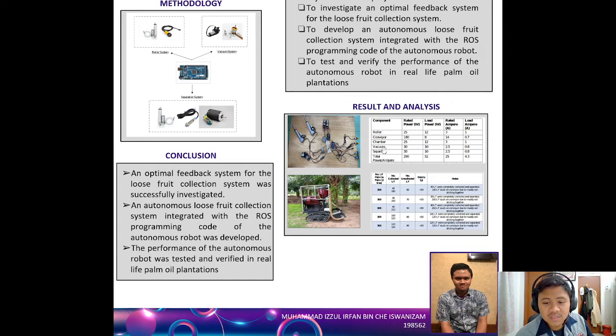It is also mentioned that the sensors are not considered in this analysis because the total watts used by each of these sensors are very low, and thus we can ignore these consumptions. And we also compare the rated amperes and the load amperes of the components. And we find that the total rated ampere is 25 amps, whereas the actual load ampere is only 4.3 amperes.